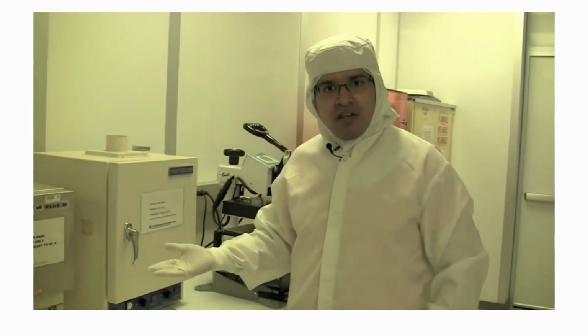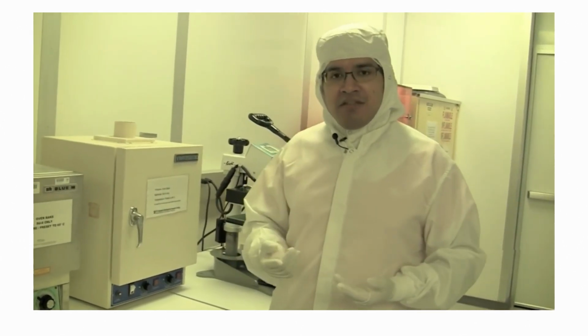Ordinarily, I would wear a particle mask because that's going to prevent you from breathing on your sample. But since we're not actually spinning SU8 in this video, I'm not wearing one. Also, I want to be more audibly clear. So SU8 generally has two baking steps. We have a 65 degree and a 95 degree step.